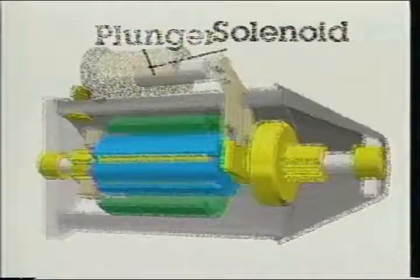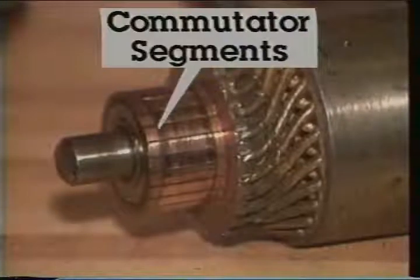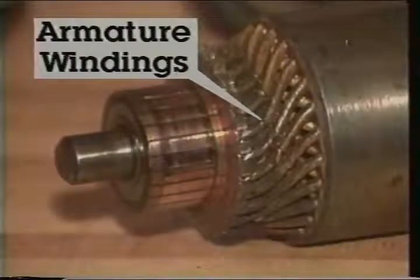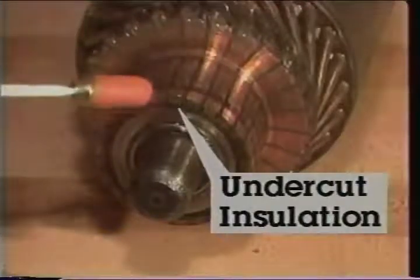Some starters use a solenoid to physically move the plunger, lever arm, and pinion gear back and forth. This close-up shows the commutator segments. Each segment is connected to an armature winding. Insulating material is undercut and separates the commutator segments. This allows the brushes to feed current into each set of armature windings individually.